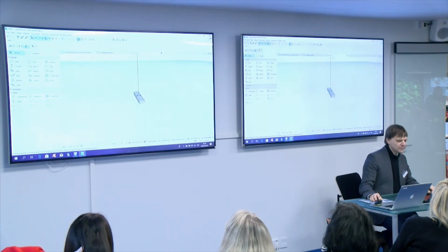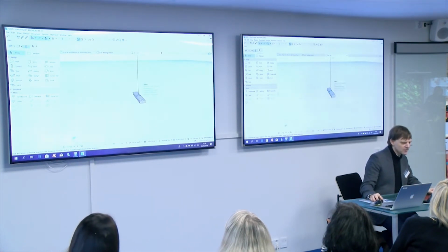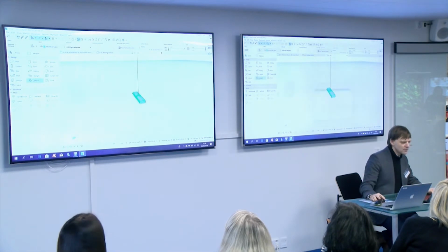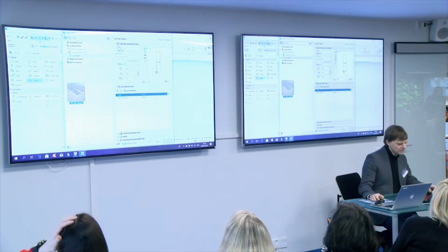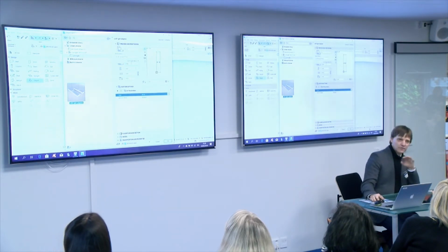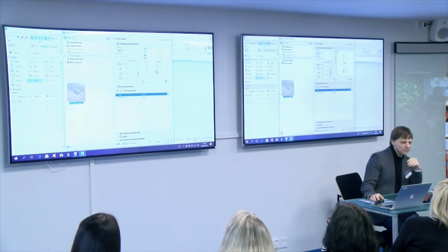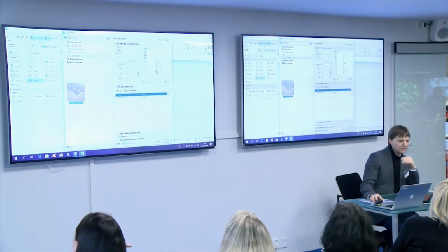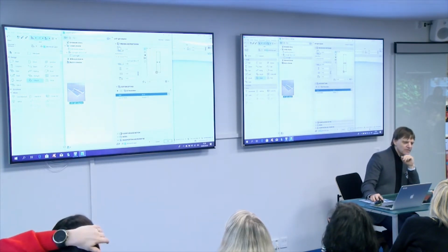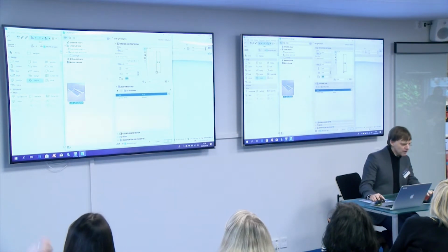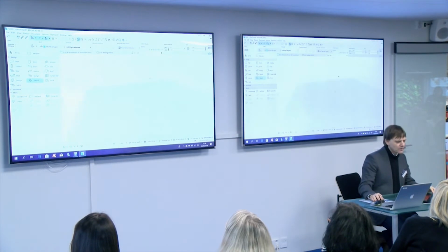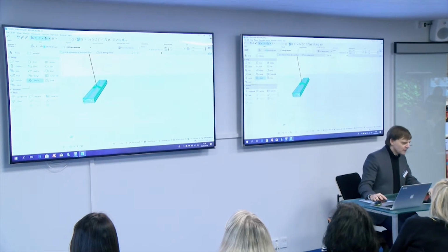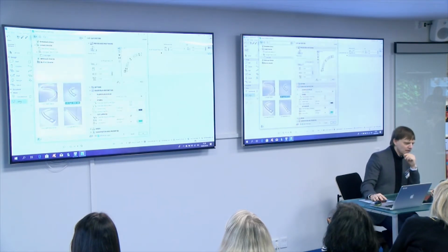As you can see, this is now suspended. It has a wire suspension. We can take it and position it on the ceiling. Let's say that it is 2,500 millimeters, 2.5 meters from the floor. And then, because I know that the standard height in Archicad of the floor levels is 3 meters, we put 500 millimeters for the wire suspension. Okay, now we can go into lamps to add our first module.